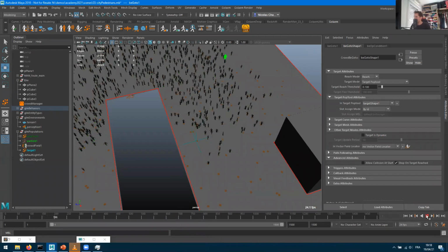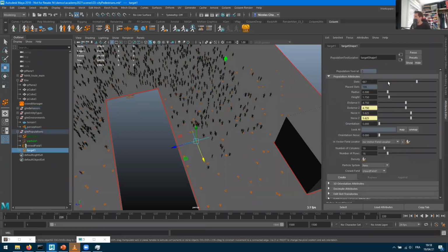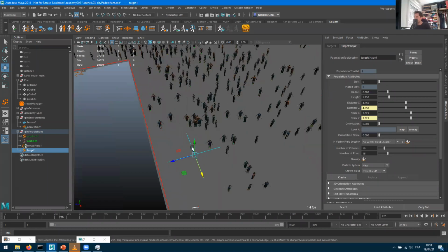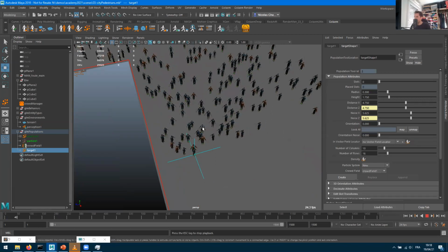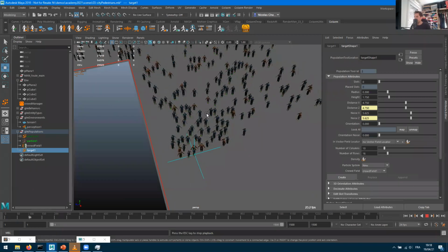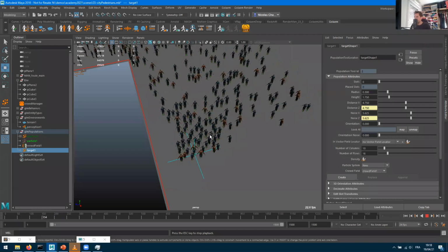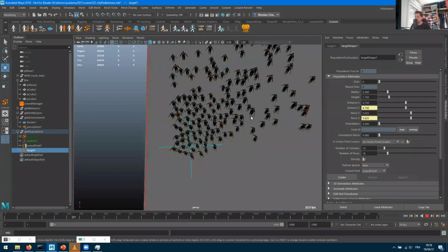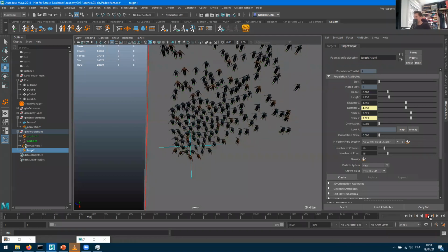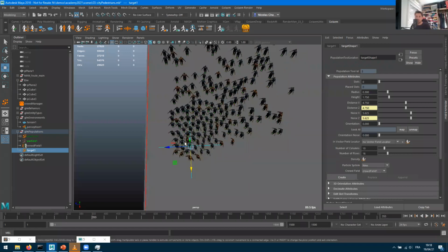And if I want, I can change my popTool anytime. Let's say I put 0 positions in it. So now my popTool is just a grid. The next time I throw the sim, I'll have all characters converging to that one and only position. And still, as soon as they converge to it, they keep avoiding the other guys, so they're all good. I could keyframe that popTool. It's just a locator, so you can keyframe position translations, and the characters will follow.